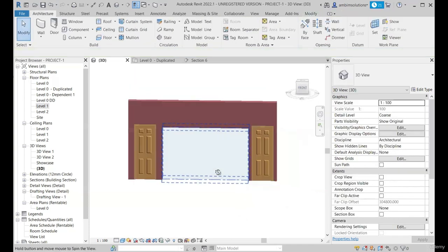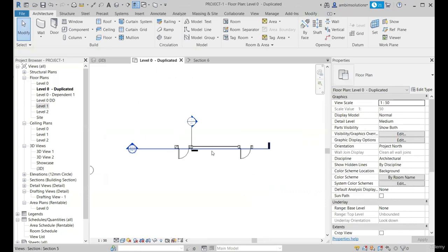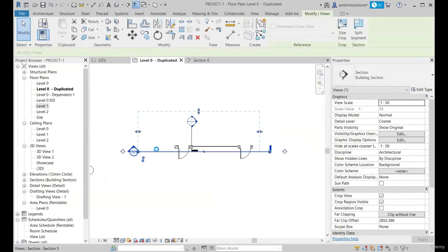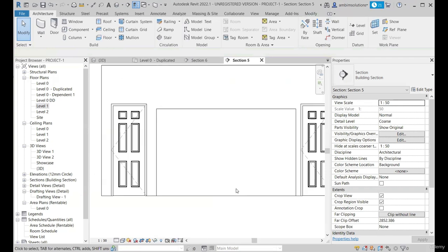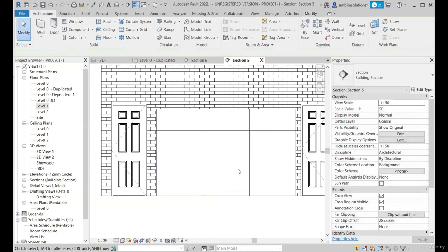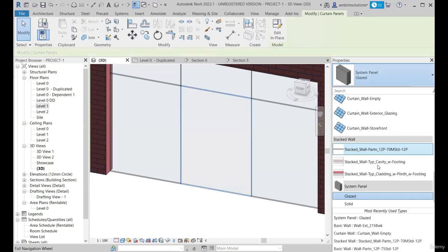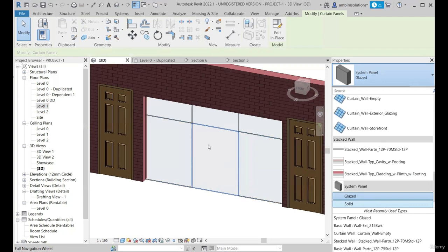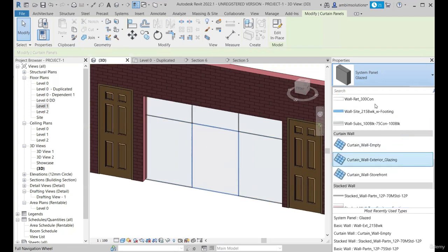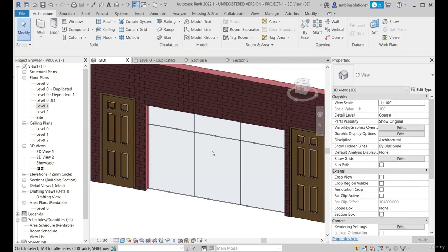So in order to place a door or any glass partition in a curtain wall, you first need to set the grid lines. I'll quickly show you, as you have seen the grid lines in the last lecture. I've just created a grid in this fashion. I'll keep this center part open, where a door would fit. Let's go to the drop down panel, and we can see there is no door actually present. Just as we have replaced the panel, like the glazed or solid, with any wall, similarly you can replace this panel with any door or window system. So let's check an example for it.